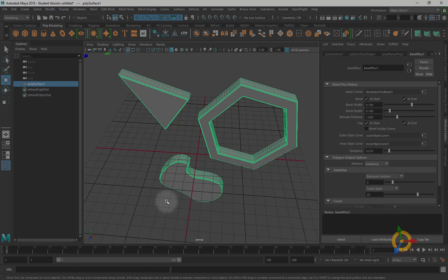I'm going to do another video and show you how you can bring just the curves in and then use Bevel Plus to individually extrude each curve. That way you can adjust the curve span number, this value here, to either reduce polygons on straight edges or increase the smoothness on curved edges. And that way you can balance your scene a little bit better. And then we'll take a look at how you can manipulate the shapes and so on, just to create a logo.